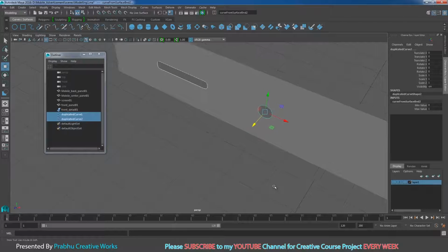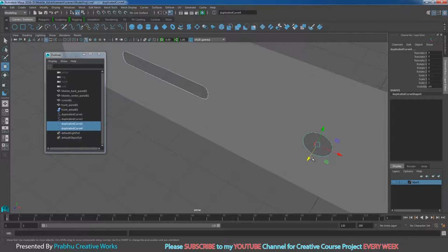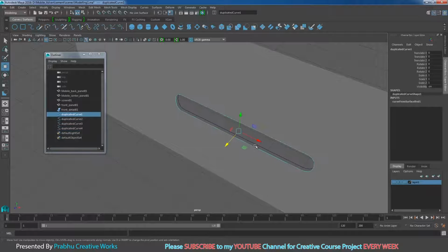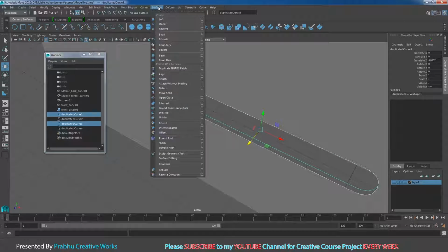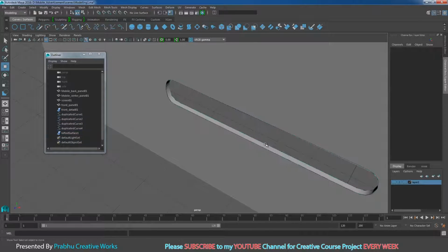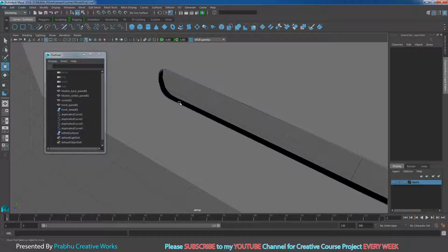So now you want to make a duplicate of these two curves. Press Ctrl D to duplicate. So you want to move it a little bit inside, like this. So I will select my node circle, duplicated curve 1 and shift select this curve and go to surfaces and choose loft, like this. So sometimes the lighting will not be shown clearly, so go to lighting and disable two side lighting. So see here our lighting is reversed on this lofted surface.